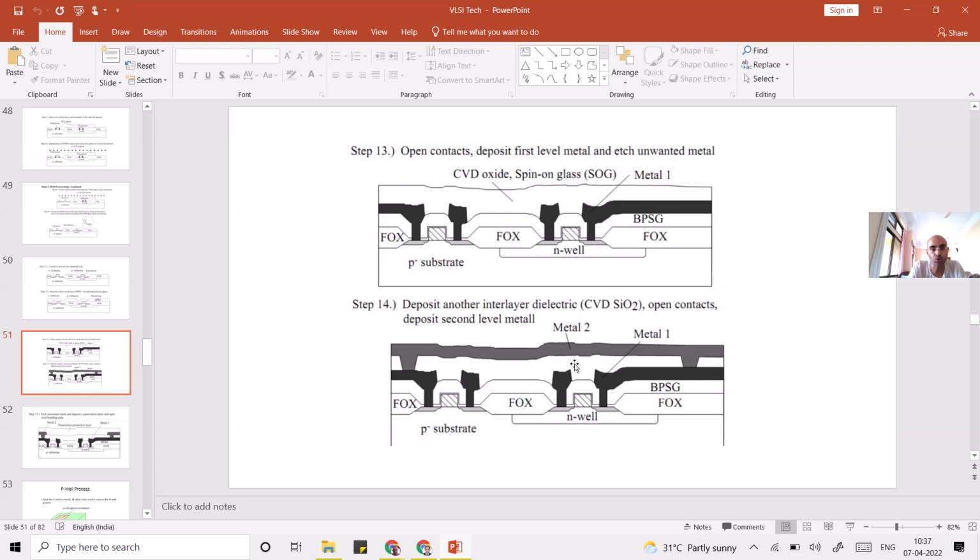Okay, and if these particular metal layers have to be connected somewhere to the device, then they are connected with what are called vias. Okay, so these are vias, which are like holes drawn into this insulator layer, and through them the wires are connected to the other wires. Okay, at the other layer.